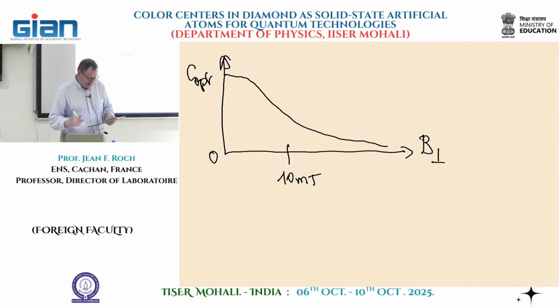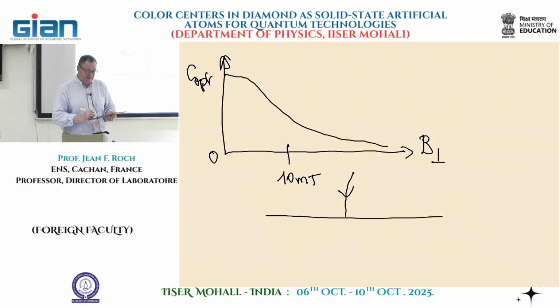Okay, just suppose now I implant an atom. This is the beam, and the implantation usually leads to a distribution like that of the atom. So you don't know where they are within this kind of pear-shaped distribution. And the distance here will depend on the energy. So if I have, for instance, an energy of 30 kilo electron volts, which is often what we use, usually we implant N2 molecules.